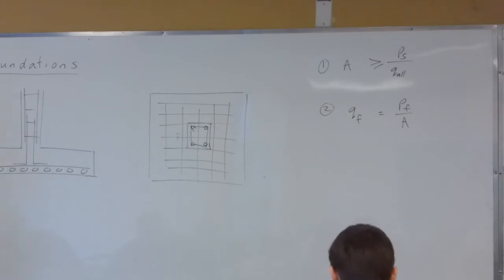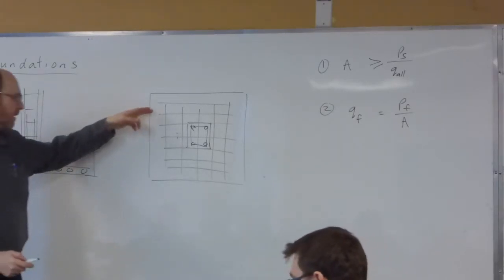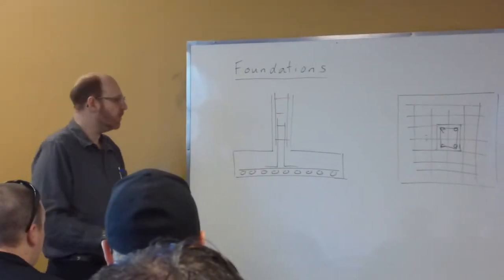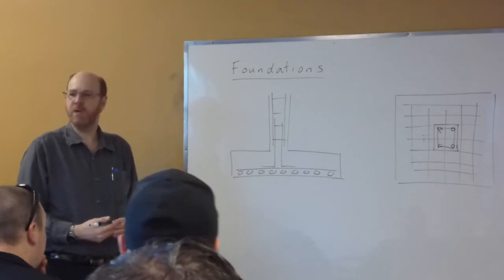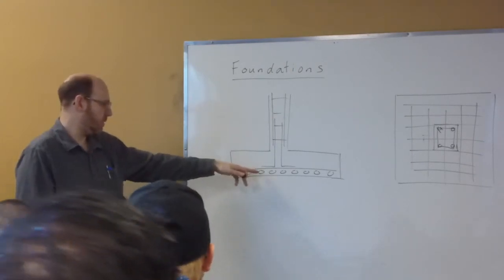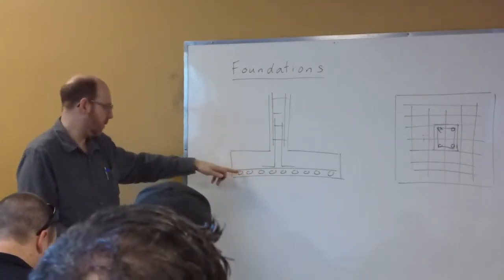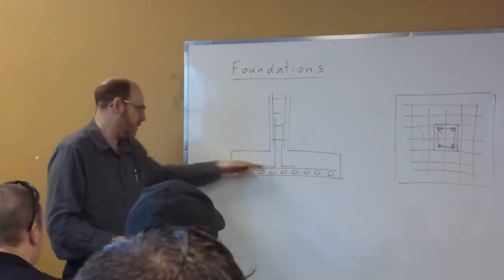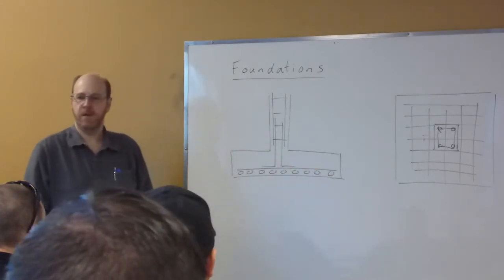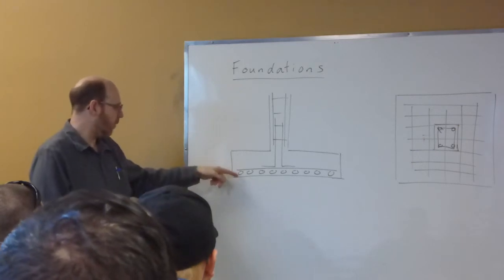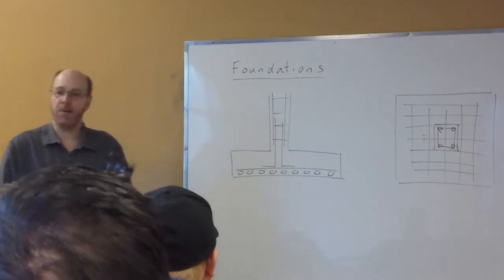And you'll notice by the configuration that we have in here that what we have in our footing, there's basically reinforcing at the bottom of the footing going in both directions. So from the perspective of a square column, it really doesn't matter which is on the top or the bottom, right? Whether these ones are on the bottom and this one's above it, or whether they're flipped around, right? Because what these are there for is our bending, right?